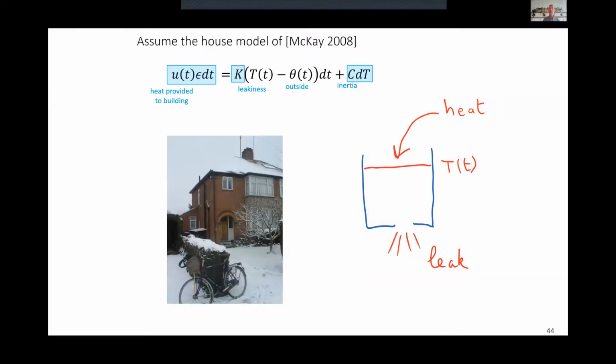For this, we can simply use the simple house model we had before. The same conclusion will be true if you use a more sophisticated model, but this house model will give us the true reason here. Remember from the house model that we used last week, that energy that we put into the house, bought from the grid, converted through the heat pump, or directly through a resistance, is put into two places. It's put into the air. This is captured by the leakiness, the outside air, or into the walls and the furniture and the inside air. This captures the inertia.